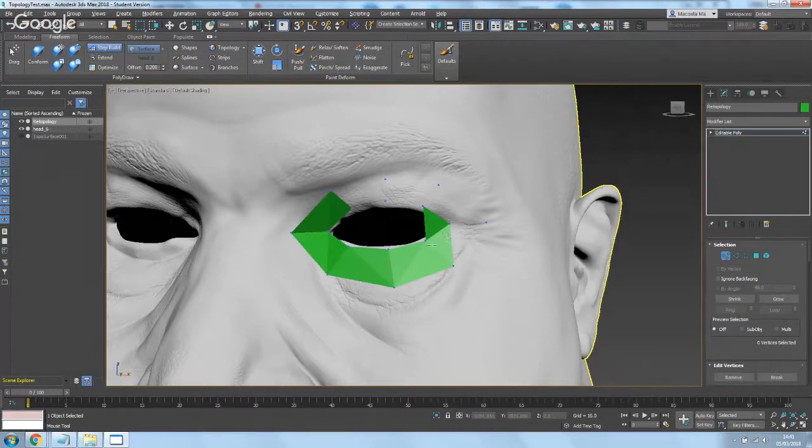So if it goes wrong like that, it just flips up into that area. Just Control and do, and then just come in from another angle and then come across again, and it will fill it for you. So there's our first set of polygons. Now to move individual vertices around, hold down Control, Shift, and Alt at the same time. Sounds a bit convoluted, but it does work quite well, and it's quite intuitive once you get used to it.